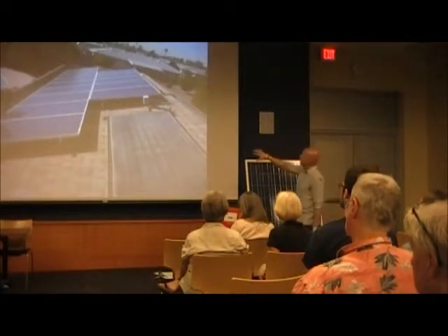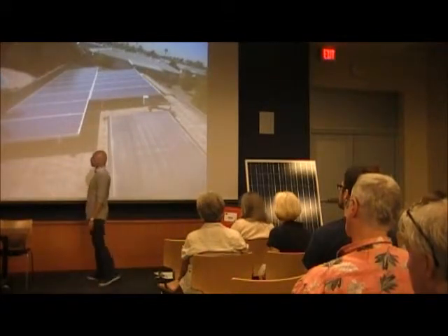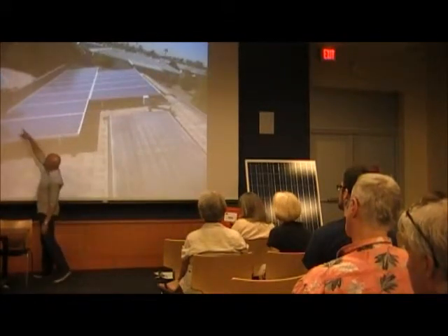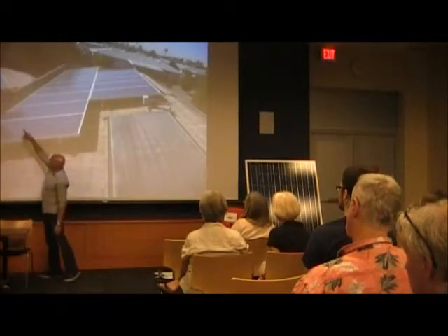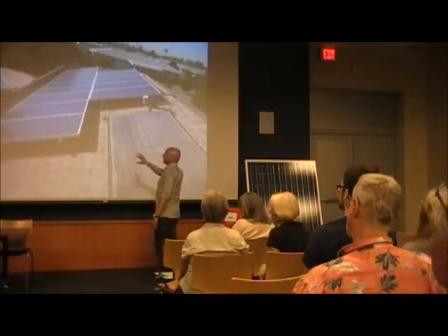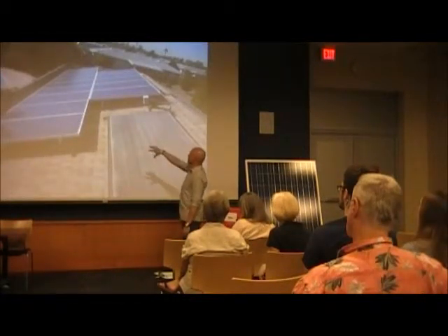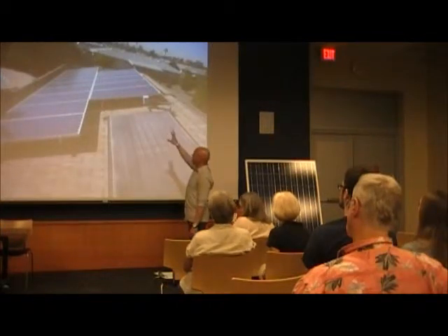But you gotta be smart about how you install. First thing, I walked up there, and I was like, "You got a problem up here?" He said, "What's that?" I go, "You see your dish right here? That's a shading issue." If all these are in strings, and I shade a module, that'll knock out that whole string. So I told him, you might want to move your dish, because you're not getting as much production. Every time you have these in strings, shading is your worst enemy.